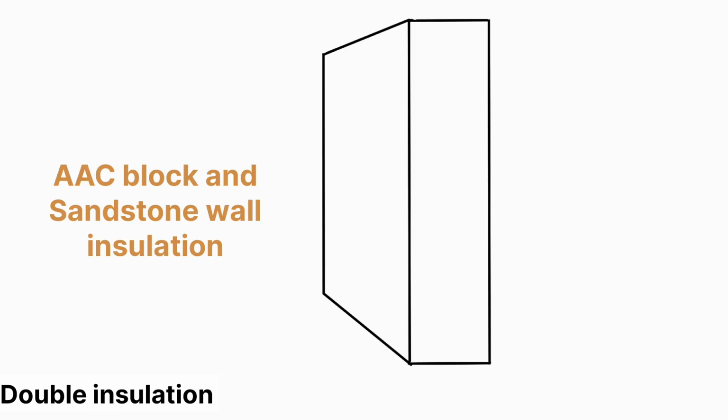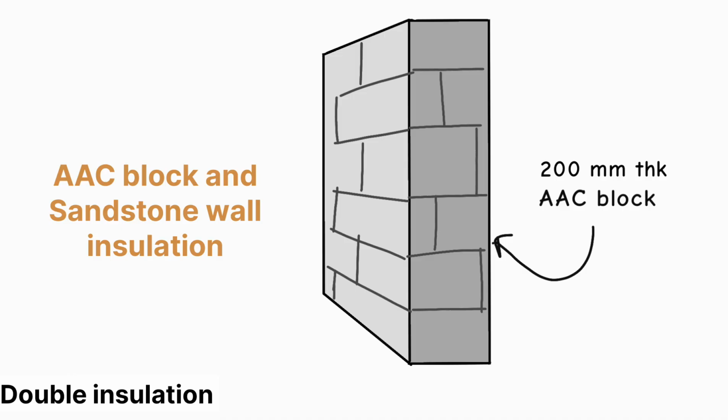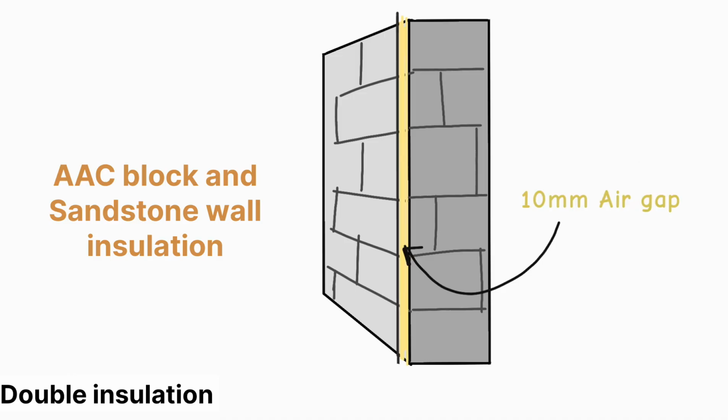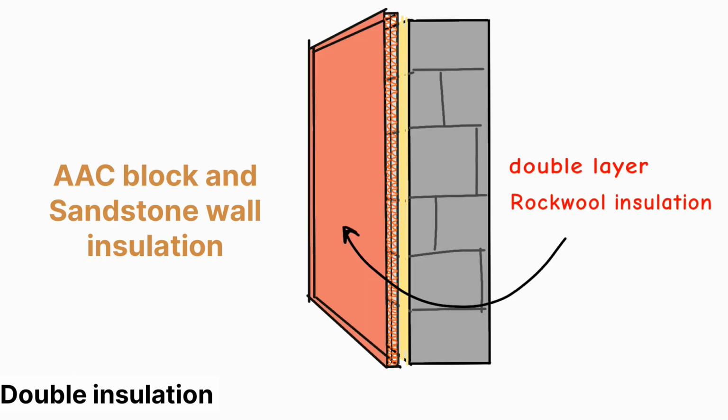In passive design, an insulated double wall functions as a highly effective thermal barrier, significantly reducing heat transfer between the interior and exterior environments. This strategy typically involves creating a cavity between two layers of wall construction, which is then filled with insulating material, like mineral wool, cellulose or foam, or sometimes even left as a sealed air gap.